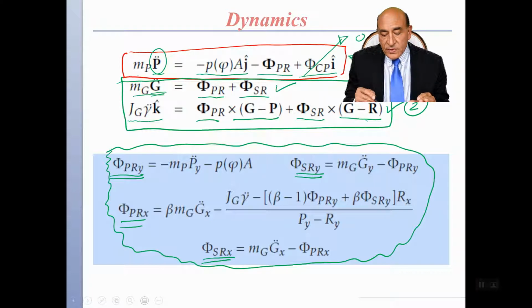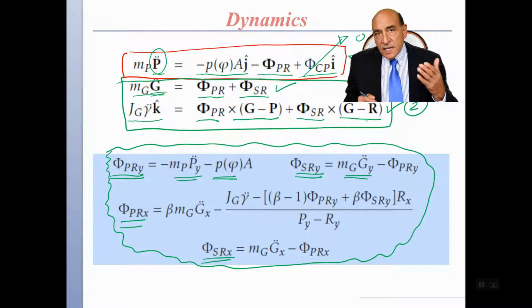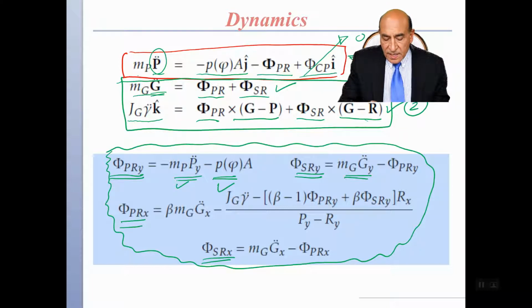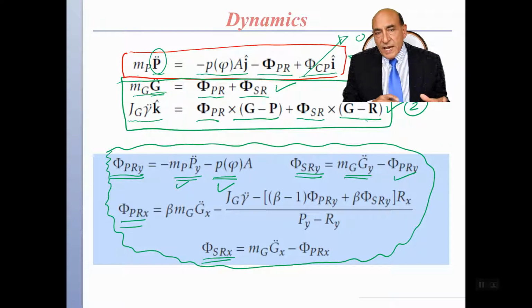system. And the driving system for us is a pressure, so this drives the rod, and accelerations. So in terms of accelerations and pressures: once we know the input to the problem, pressure as a function of angle and acceleration coming from the kinematics, we plug in here and plug in here and find the phi, and then plug in the phi successively and solve this system of equations. And that is what we have a MATLAB code for, to solve the system of equations and give us these forces as a function of the angle, the crank angle, at any point in time.